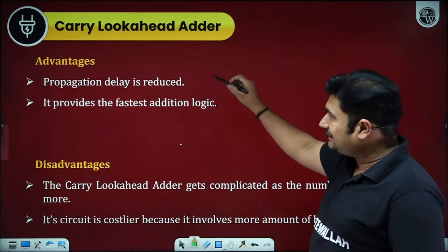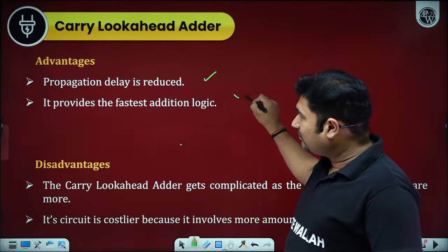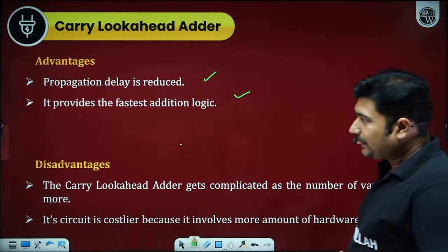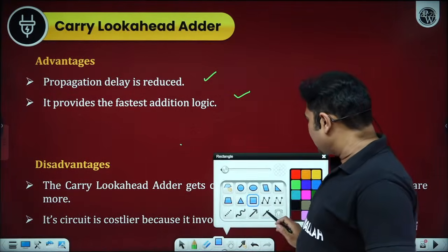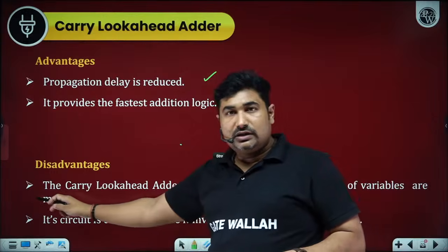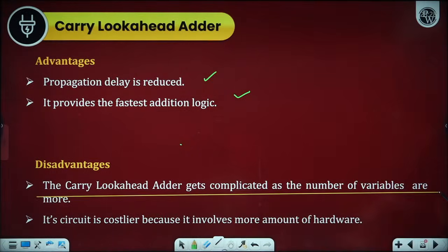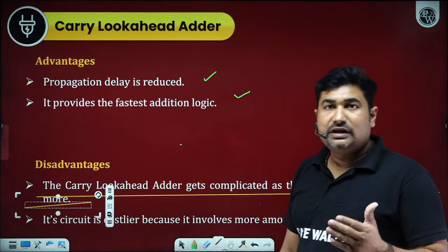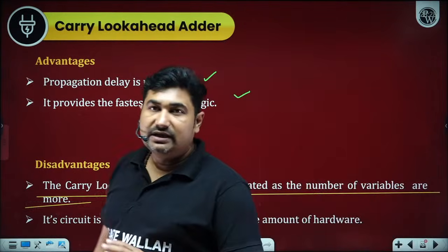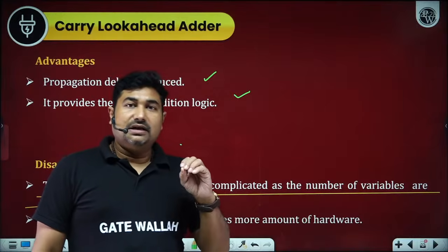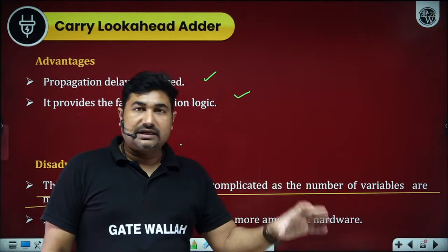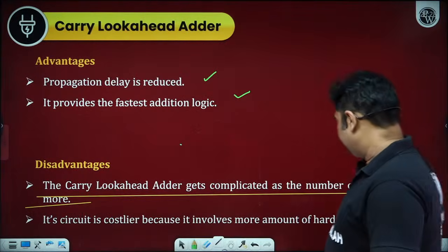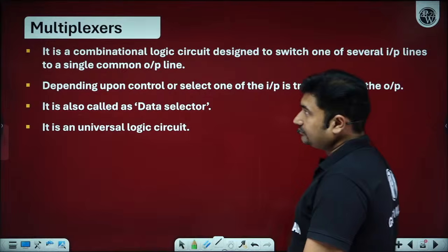So advantages: propagation delay is reduced, and it provides faster logic for addition. Disadvantage: its cost is more, and it is a complicated circuit because of the large number of two-level AND-OR and inverter circuits. So always remember that the look ahead carry circuit contains a two-level AND-OR circuit.